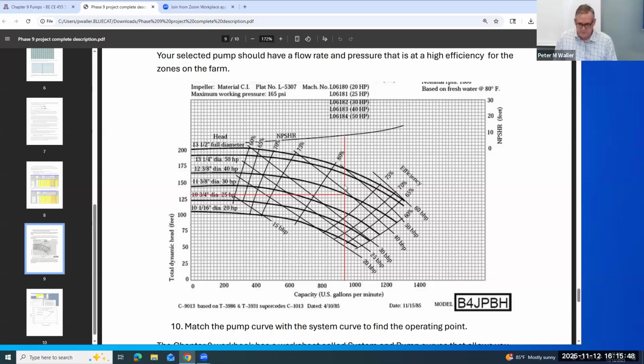Now, if for some reason they operate that pump without pressure against it and it goes out here, then the impeller curve is going to be above the horsepower curve. That's going to burn up the motor. So it's very important not to just run a pump without any pressure against it if it's designed to run with pressure against it. You cannot have an impeller point above a horsepower curve.